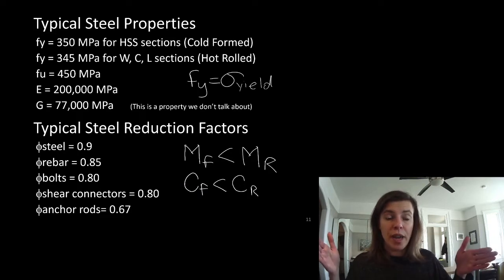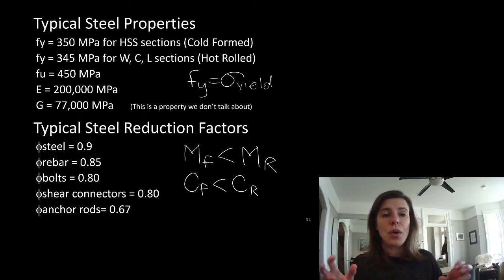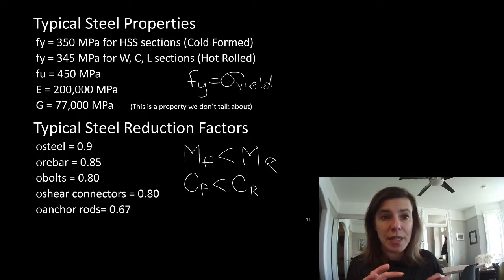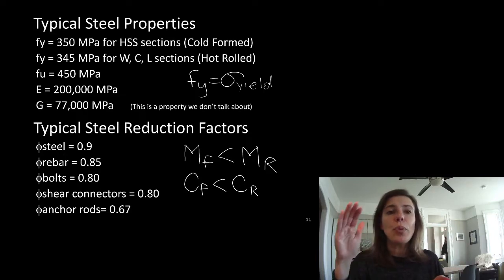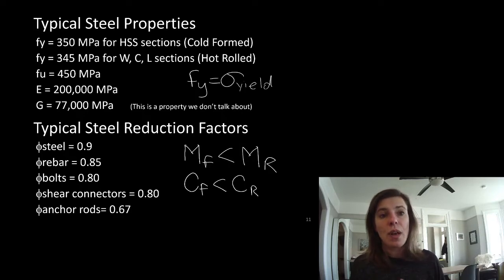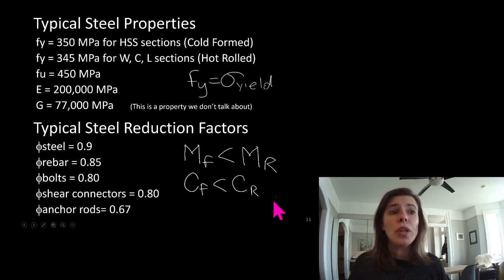Last term, we learned how to find the factored axial loads on an object. We looked at tributary area, we looked at the loads, we factored them, we then multiplied that factored load by the tributary area, and then we even drew pretty little diagrams of those elements just so we could easily illustrate what those loads looked like to ourselves. And then we would pull out, here's the maximum load we see. Well, now we're talking about this side, the capacity, or the CR.